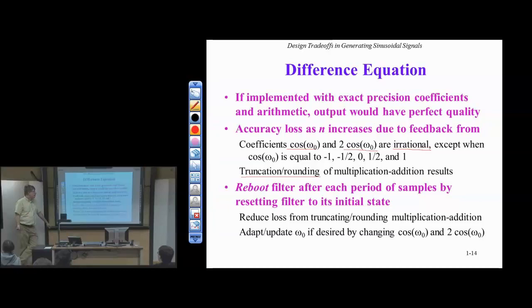And also for addition, if I were to add 2 8-bit integers that are unsigned, how many bits, worst case, do I need? If I add 2 8-bit numbers, 9, because I can get a carry. So even with addition, for every addition that I do, I lose a bit of accuracy. For every multiplication I do, the accuracy is much worse. It's the number of bits of accuracy of one of the multiplicands. It's how much I lose. A lot.